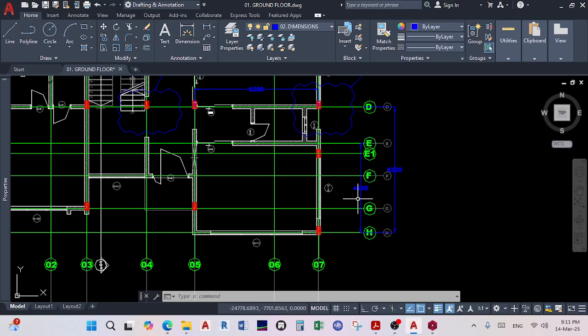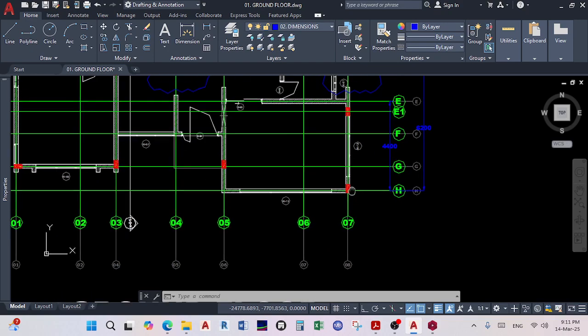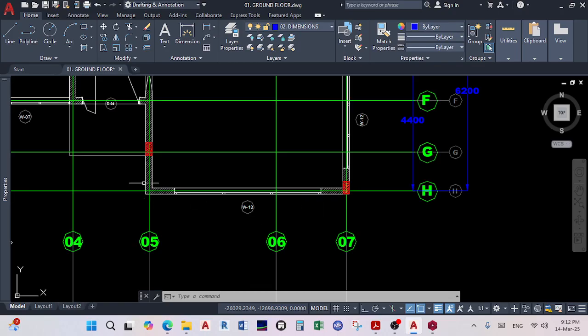You can, if you're free and if you've got the time, you can try. As long as you make the beam deep, especially this one here, so that it's the primary, and then the other one can be a secondary, and then you put edge beams around the first floor, it can work. But I decided not to do that. I would much rather be safe than sorry.